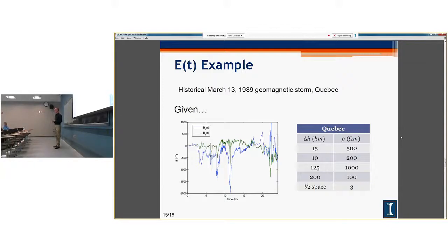And do you have any comments about the recent, maybe a month ago, there was a severe solar storm? Yeah, so that was interesting because we heard from a few utilities as far down south as Missouri, and usually you get most magnetic activity near the poles, that they had a generator trip due to high currents that were measured by a geomagnetically induced current sensor. And so they said, hey, we got this weird thing at trip. We measured these amps, and they sent us the data. He said, can you confirm this? Like, was it a storm? Like, what happened?